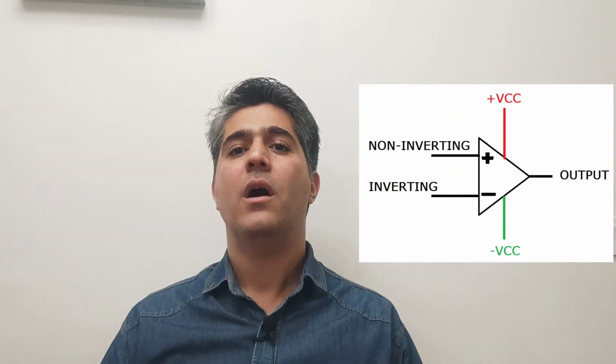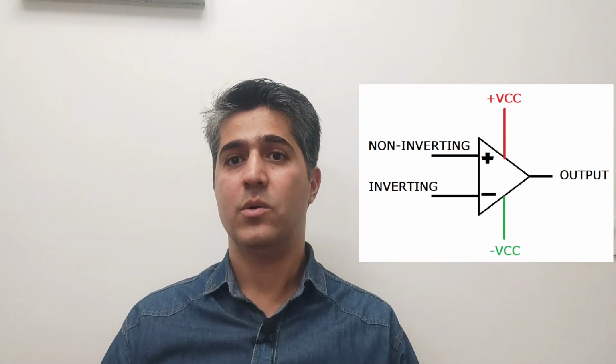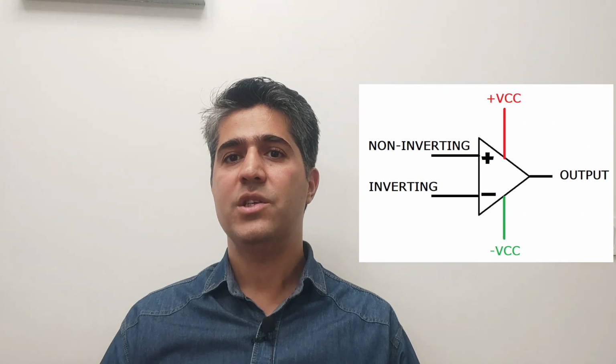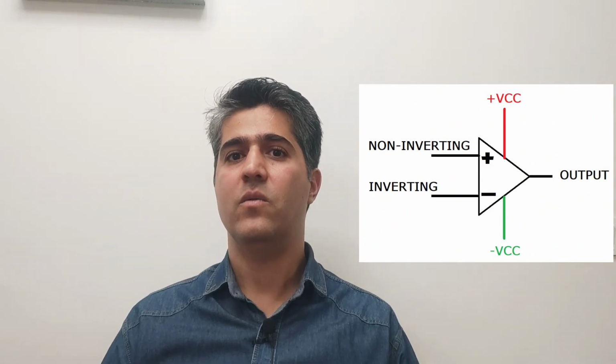In fact, an op amp is an amplifier which, according to the relationship you see, amplifies the voltage difference between the positive and negative pins by a coefficient and transmits it to the output. There is only one point: when the positive input voltage is higher than the negative input, the output will be at its maximum state, which is almost equal to the positive voltage we connected to the op amp as power supply.